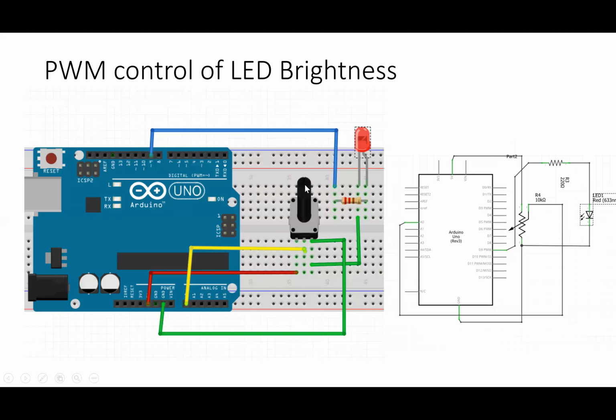Here's the circuit we're going to use to look at this to begin with. Here again is our potentiometer. It is connected to A0 on the wiper. So as this goes from 0 to 5 volts, that is connected with A0 and read by the Arduino with that sketch loaded. Pin 9 now is connected through a resistor and an LED to ground. And so whatever voltage appears on pin 9 will make the LED turn on. Here is the schematic circuit, not very complicated, so I'll let you look at the downloaded file if you want to look at this carefully.